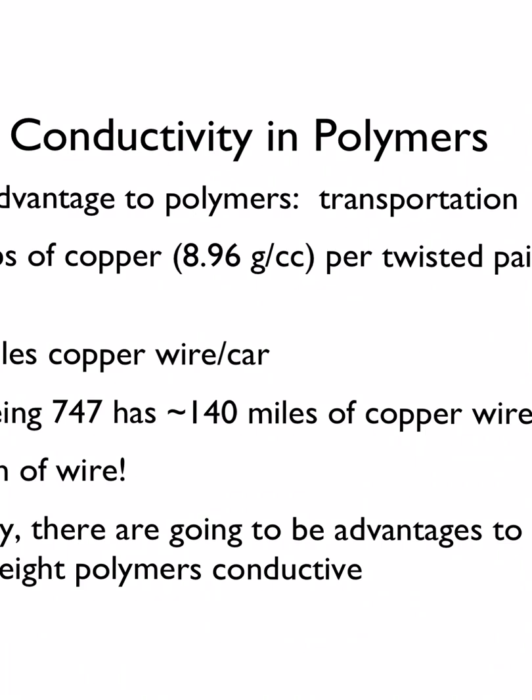In cars. And of course, we've seen that aluminum can get replaced in planes in the 767 and up, or 777 up, whatever it is. They replaced a lot of the aluminum frame with composites, because aluminum, which I think is 2.6 grams per cc, was just too heavy. So they went down to composites and cut the density in half, and that's important in the context of these types of trade-offs.